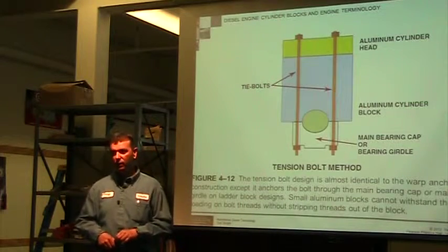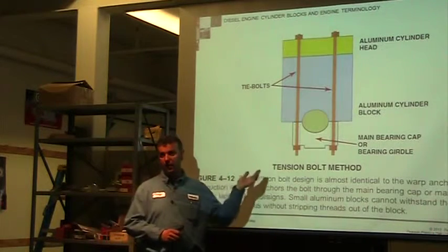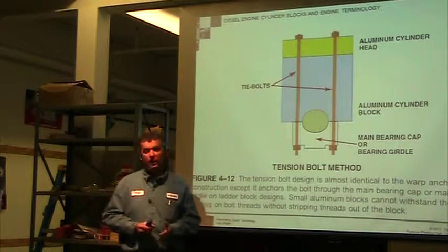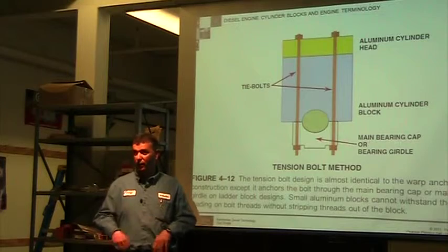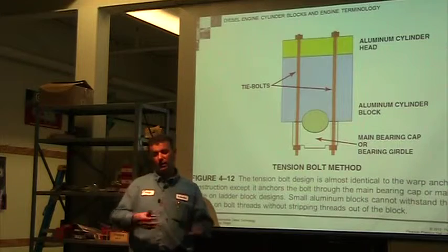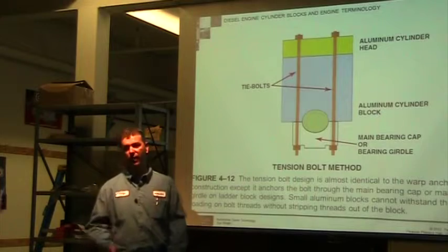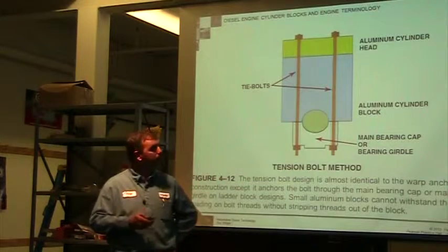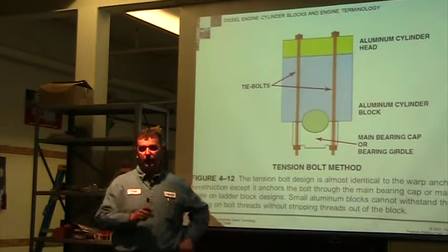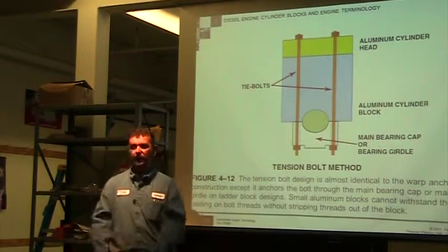If I was in the golf world and I don't want compaction, a fairway mower, yes, I might consider something like an aluminum block to keep the weight down for compaction reasons. But remember, weight is also what gives us traction. So we incorporate some of that weight in our traction. It's kind of a give and take, and for the most part, it's not a major thing in most of our equipment, so we just don't see it. We'll probably see more of it as the technology improves. Once we start getting blocks that are really strong, they'll start shrinking it and adding it in here.